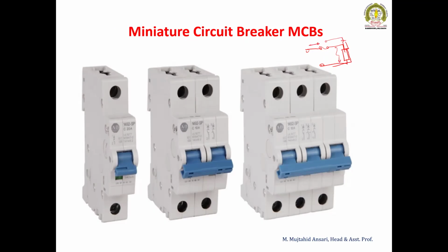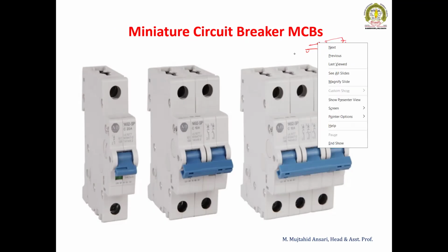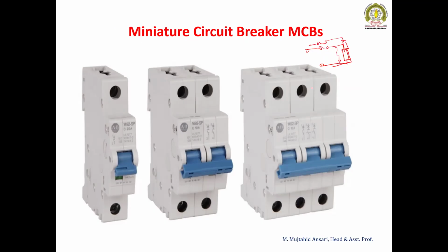But these fuses are rewirable. Now we have to replace the fuse with new wires, so it requires some time, and there will not be a proper discrimination. Say for example, the load wants only 10 ampere maximum current, but the fuse wire is wrongly installed, and it carries 16 ampere or 22 ampere. Definitely the fuse is not going to blow out, even though the current is more than its required capacity, meaning the load capacity.